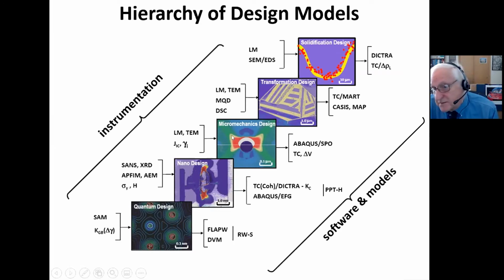Equally important are the material science models that constrain scale-dependent processabilities, and that's the solid-solid and liquid-solid phase transformation models, which, through the ICME technology, we can then link to macroscopic process models where largely scale dependence comes through heat transfer.